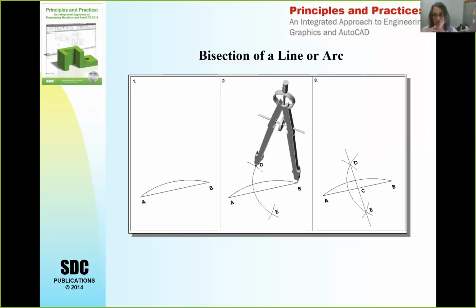If you do want to get one of these, you see this screw piece here, it's important that you have a screw setting on your compass and not just a slider. The slidey ones slip and don't hold the same radius setting. And you'll notice as I'm demonstrating these that although this has angle measurements on it, I don't use it to measure angles when I'm doing things like transferring an angle. I use the construction techniques because they are going to be more precise.